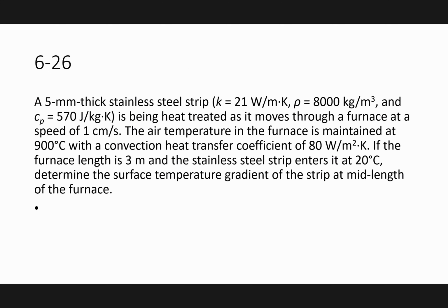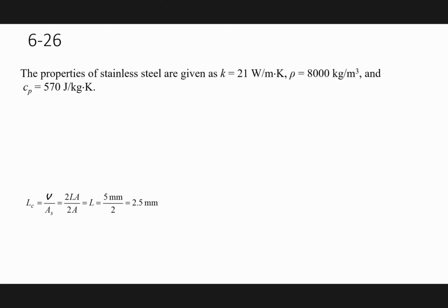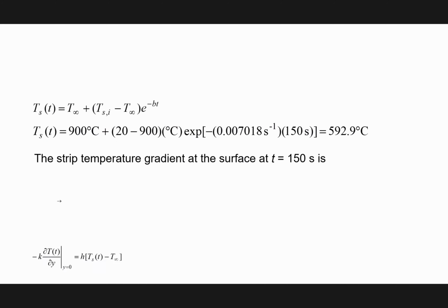Okay, but the question was asking something else. The question was asking here is determine the surface temperature gradient of this. The surface temperature gradient. Surface, how can I do this one? Well, we have an equation for the gradient. The gradient at x equals 1.5 would be minus h over k times the temperature difference. Excellent. Therefore, we go back and we calculate this temperature gradient.